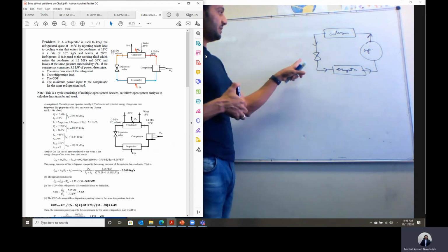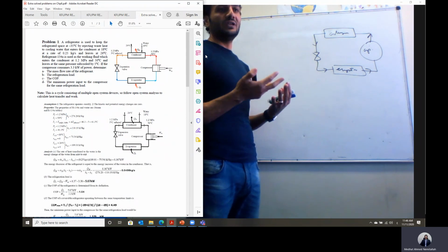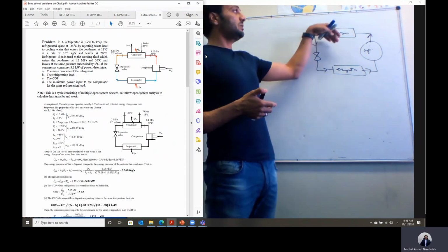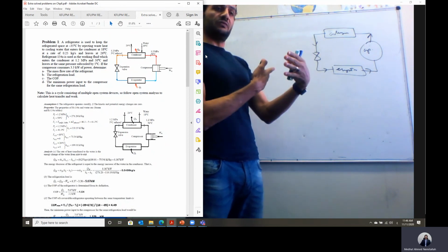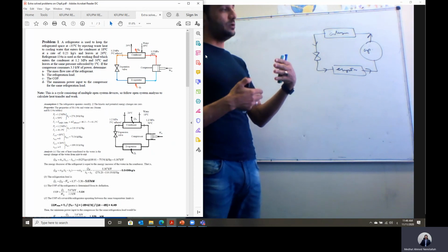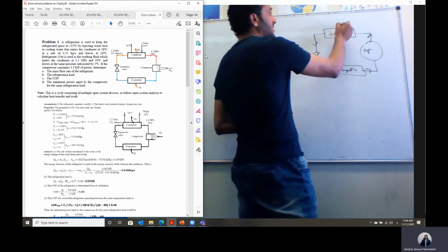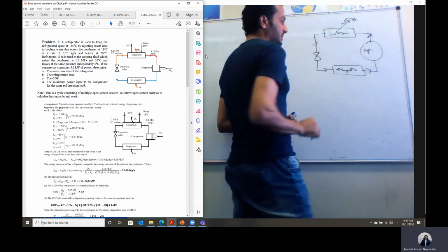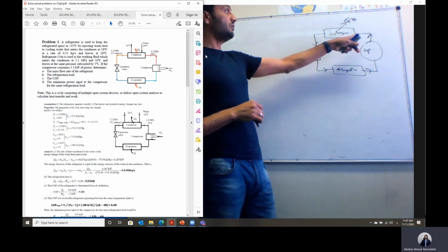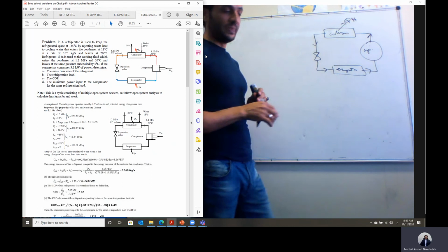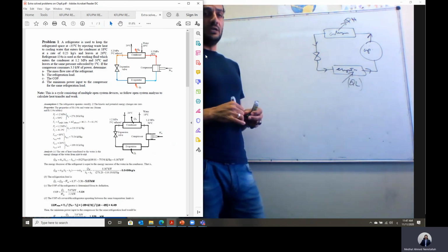He said this is a kind of big refrigeration cycle. Usually in a refrigeration cycle like a small fridge, the cooling load is low. So in this case, the heat rejected can just be rejected to the surrounding air. We have a set of tubes, we pass the freon inside, and as we use more tubes, we increase the surface area exposed to the air. So the heat, Q high, will be rejected to the surrounding air. The surrounding air in the kitchen can cool down the condenser and convert the refrigerant from the vapor phase to the liquid phase. And this is the evaporator, where heat is added, Q low, which we call the cooling load.